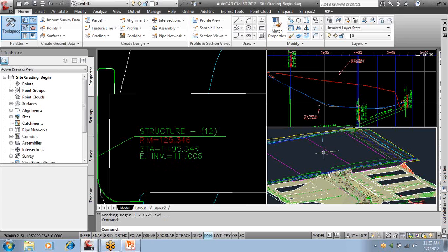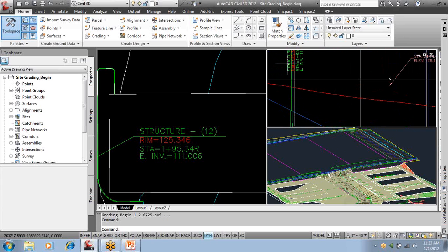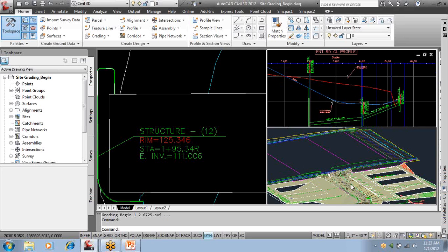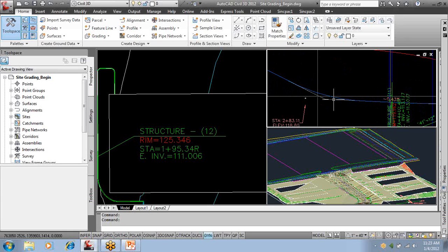The bottom right is going to be your site design, where we already tied in the road design and we daylighted to the surface. And this is the profile where the storm sewer is already designed, and you can see using the rim elevation from the existing, the new road right here. Okay, so this blue line is the new road that's designed, and this at the bottom is calculating the rim elevation from that new roadway design profile. So assuming the structure is right in the roadway, right on that center line.